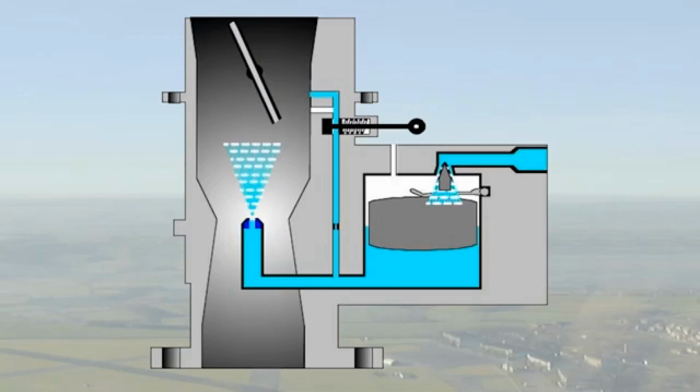As the throttle is opened, the depression at the lip of the throttle valve decreases, and the depression in the venturi increases to the point where the main jet starts to deliver sufficient fuel, and the flow through the slow-running system slows down.